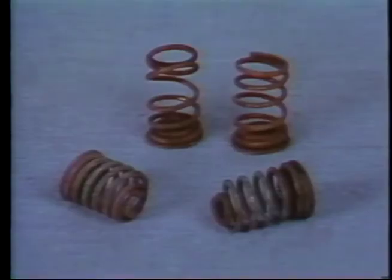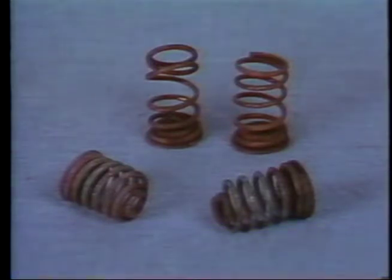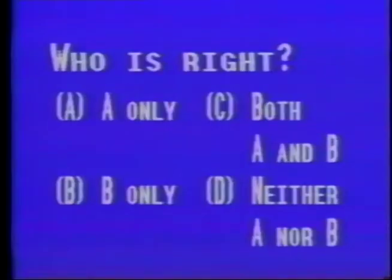Technician A's statement is true. Weak return springs can cause the brakes to grab. They can also cause the brakes to drag. Technician B's statement is false. Weak hold-down springs will cause the brakes to grab also, but will not cause the pedal to be spongy. So the correct answer is response A.